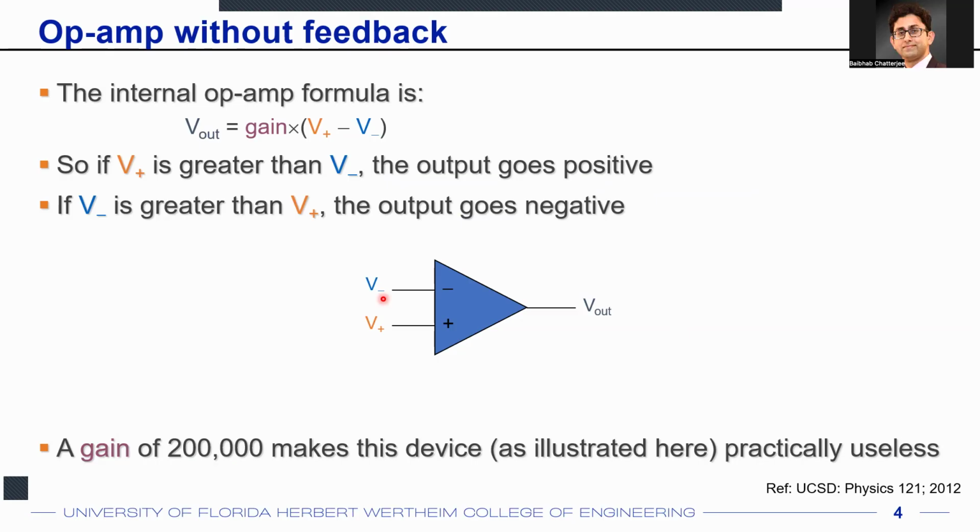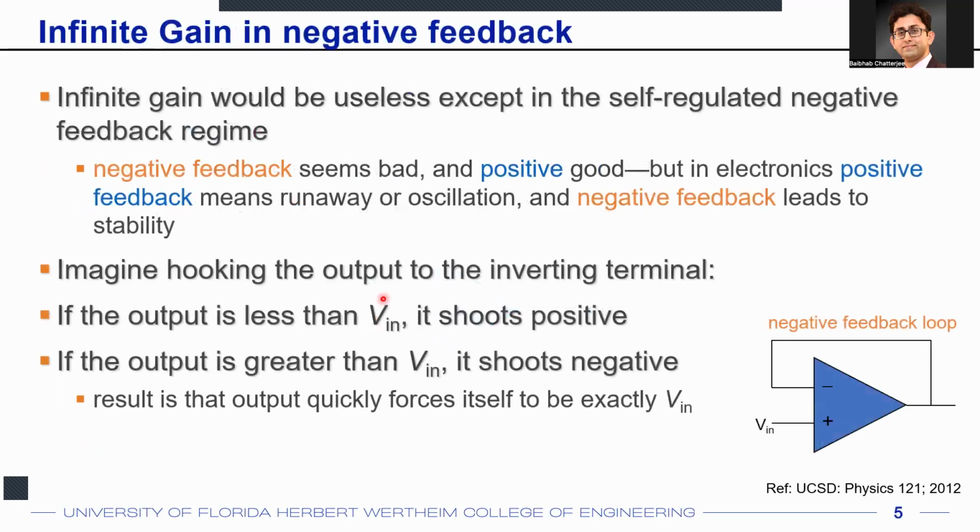And that's why generally you use the op-amp in a negative feedback loop to have a more stable gain, as you have seen in the feedback slides. Also, at the same time, it becomes more useful. Let's say you amplify the 1 millivolt signal to 100 millivolt. So you just need a gain of 100 for that. So you can apply a closed loop feedback for the open loop op-amp and get that kind of gain.